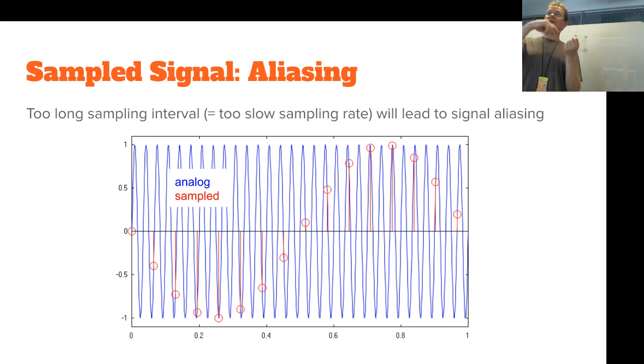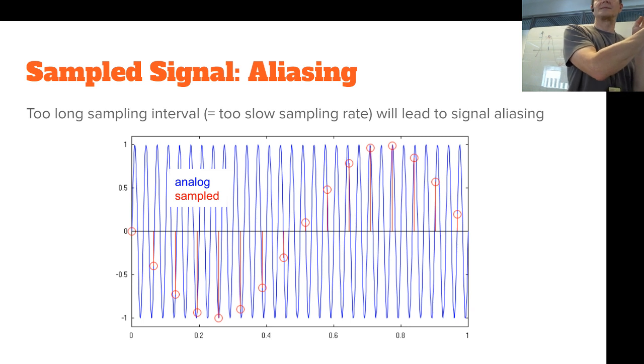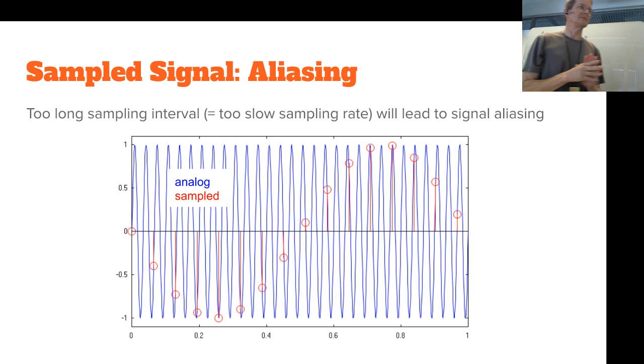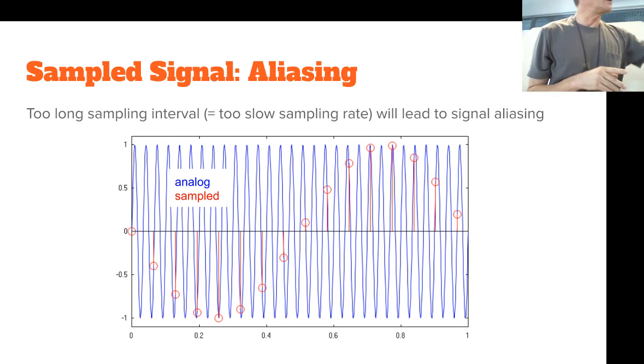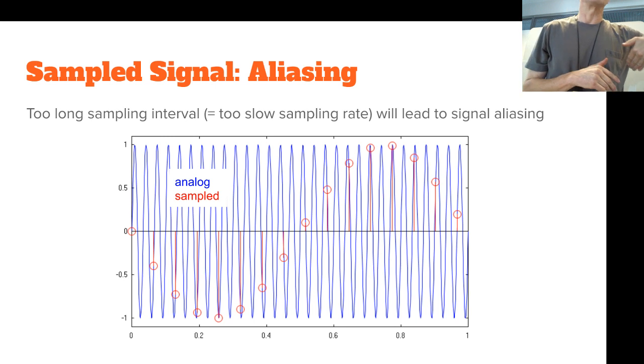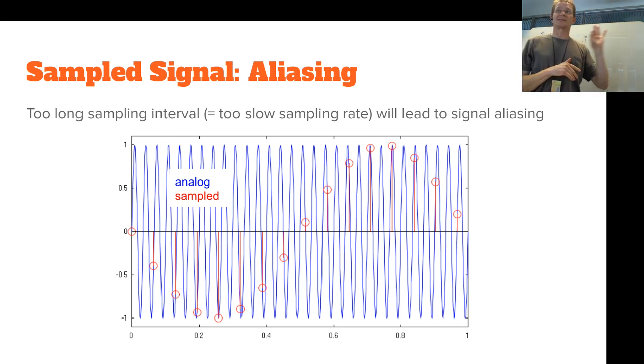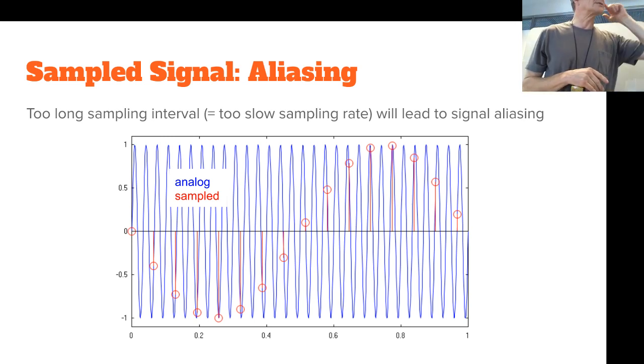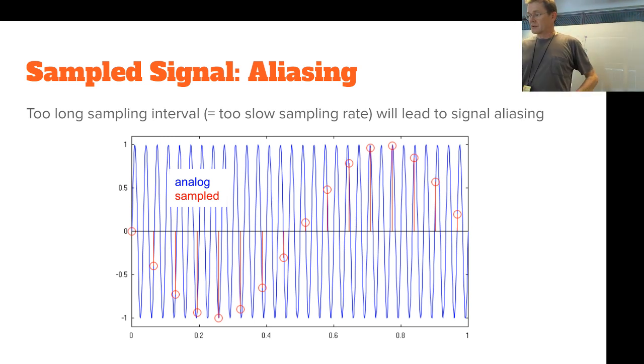What else? Then you have noise on the system. Always when you measure anything, you have noise. So if there is any high frequency noise, you need to use a low pass filter to filter it out before sampling. That's why I have the anti-aliasing filter on the schematic of the design.